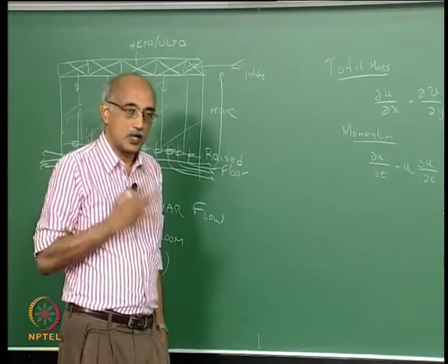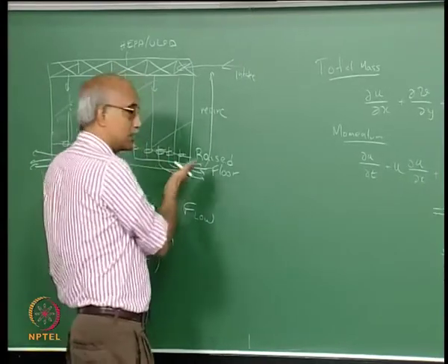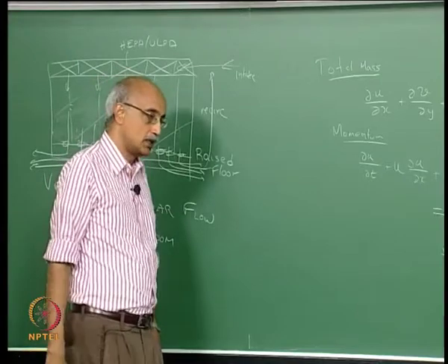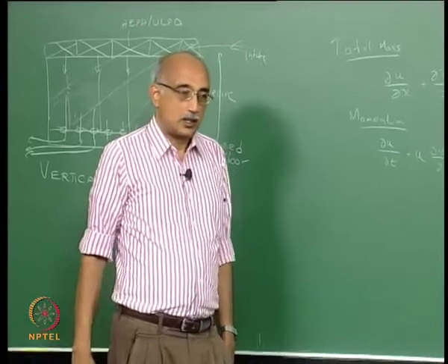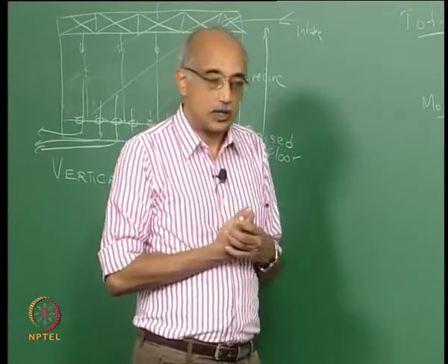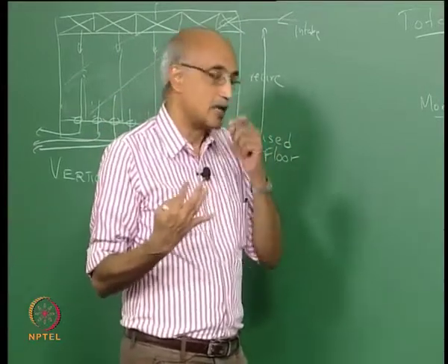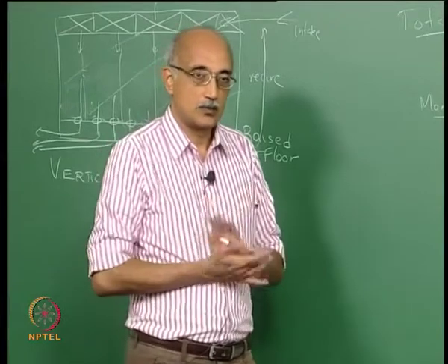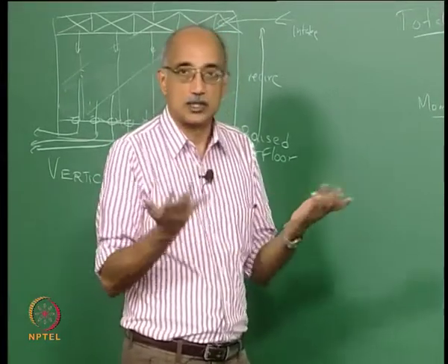You have to apply the appropriate initial conditions and boundary conditions. For example, the initial condition for such a facility may be that the starting point of a clean room is where essentially there is no source of particles inside the clean room, and all you have is air entering and air leaving. So, you can look at the time 0 point as a steady state where essentially there is no contamination source in the clean room.